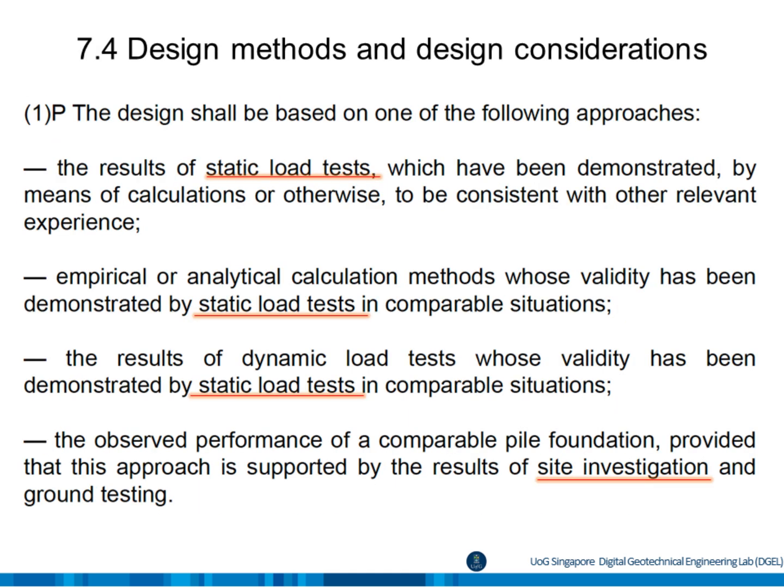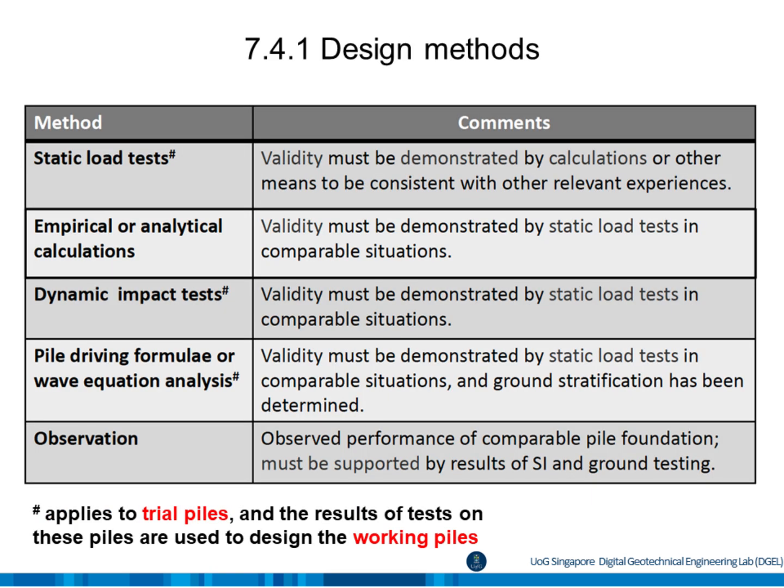According to EC7, pile design methods are based directly or indirectly on the results of static load tests, meaning full-scale field load tests. The results from a specific site form the direct basis for the design. If you use calculation methods, your calculations should be verified against field load test results. And when using static load test data, it is important to consider the actual loading conditions, as well as any potential changes in the ground or groundwater conditions. Here, I've summarized the available design methods.